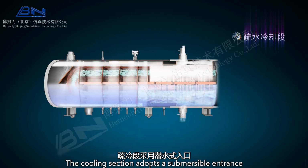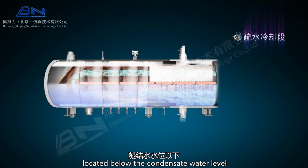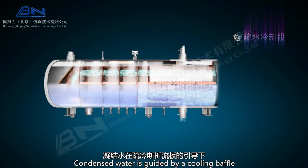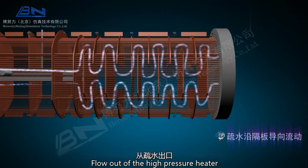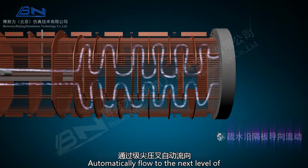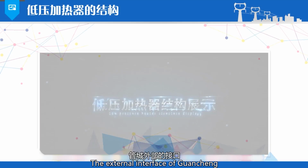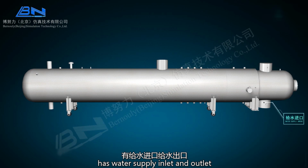The cooling section adopts a submerged inlet. The mouth end of the inlet is located below the condensate water level, making it impossible for steam to pass through. Condensed water is guided by a cooling baffle to flow along the axial direction and out of the high-pressure heater. At this level it passes through the drain outlet and automatically flows to the next level of high-pressure heater through the pressure difference.